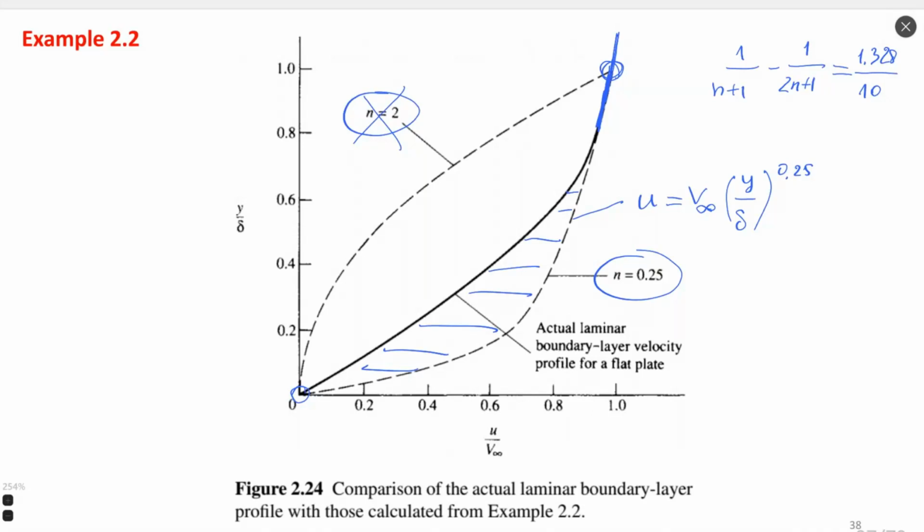Because if you remember, I told you at the beginning of this lecture that the control volume approach uses a global balance and calculates a global balance. So it does not see any particular behavior or any point values of the velocity profile. It calculates just a balance. For the model of the boundary layer, the global balance is to satisfy the condition of 0 velocity at the 0 point and infinite velocity at the infinite point. So this is a balance. These are the balance criteria for boundary layer theory. This is why we have no correspondence in the middle. But in general, globally, we have a solution.